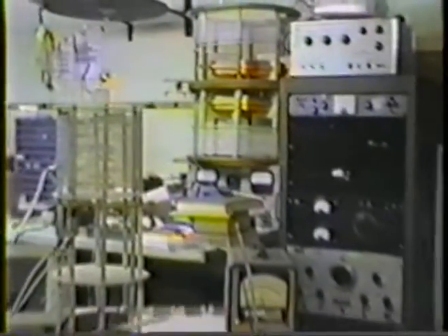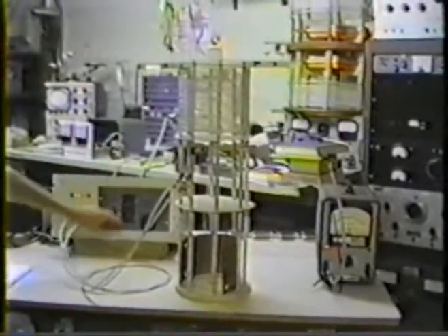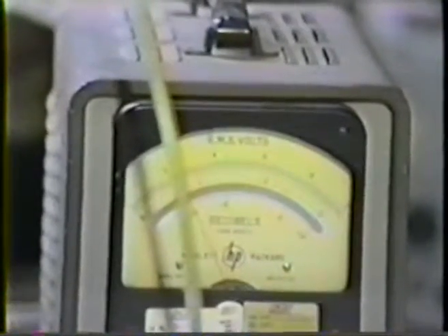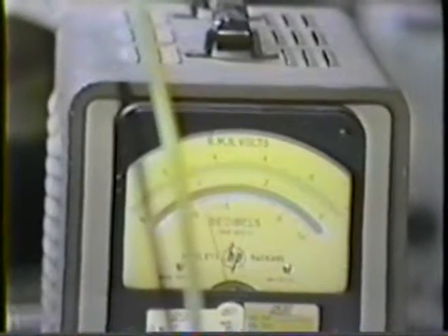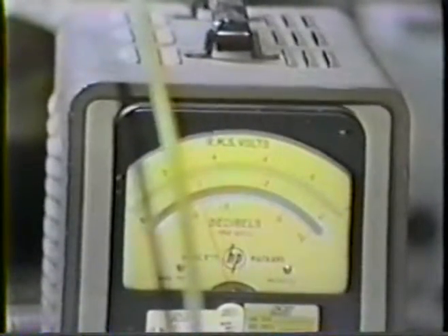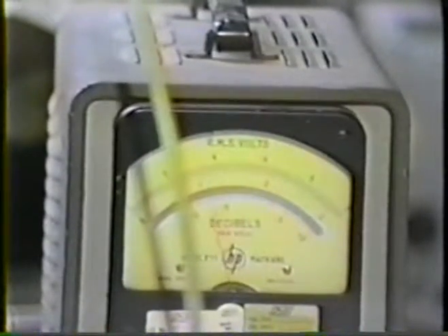So we have a very light coupling between the end turns here and the probe wire, which of course goes to our same voltmeter. So what we'll do is we'll sweep around with the oscillator again and find out what kind of resonance characteristic we have here. Now we notice a difference right away. The resonance of this type of wave is much sharper. Rather than varying over several hundred kilocycles, now I'm varying over several kilocycles. So we're talking about a sharpness factor, or a Q, of 100 times greater.